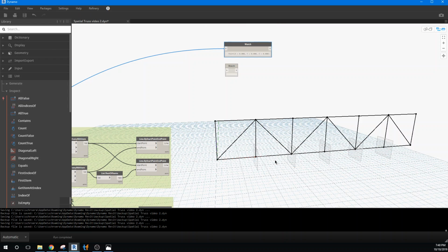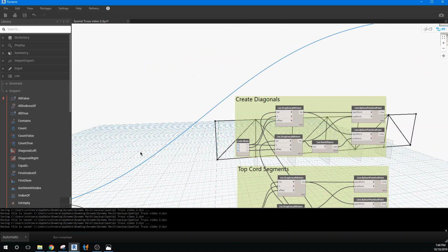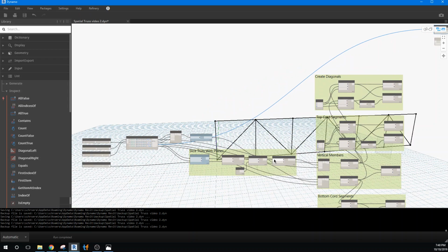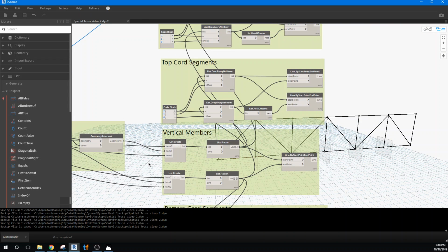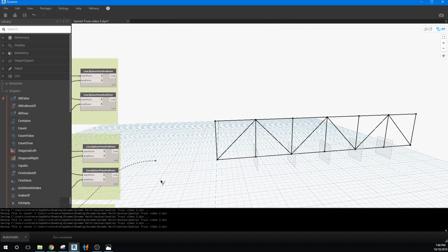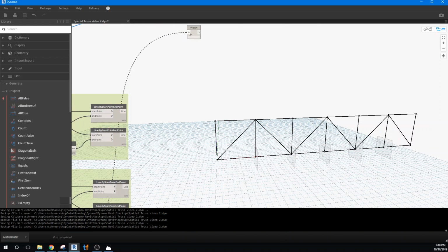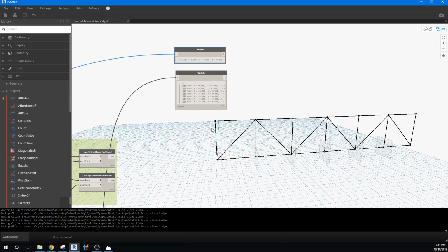And the other one is the list of all the points that go along there. So we can pull back here and find the list where we've added all the lists together and flattened them out. We have 7 points for the bottom of the chord. I'm going to pull that one up and place it in the second watch box. Those are all the bottom points of the chord. They all have a 0 value for Y, the height of the chord for Z, and then the different coordinates as they go out along the x-axis.